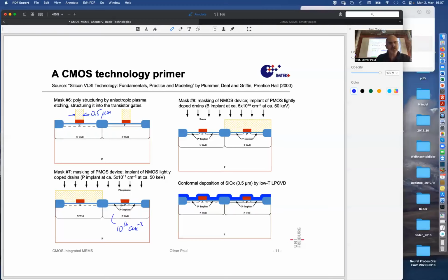And these electrons can then flow across this P region underneath the gate in an inversion layer that allows these electrons to flow along the gate oxide from source to drain. And this is done actually by a pretty heavy doping. The sources and drains ultimately will be pretty heavily doped. But if you have these very heavy dopings, and by heavy, I mean to saturation, 10 to the 19th, then you also have very strong PN junctions, because you have an NP transition. And PN junction with high doping mean high fields.